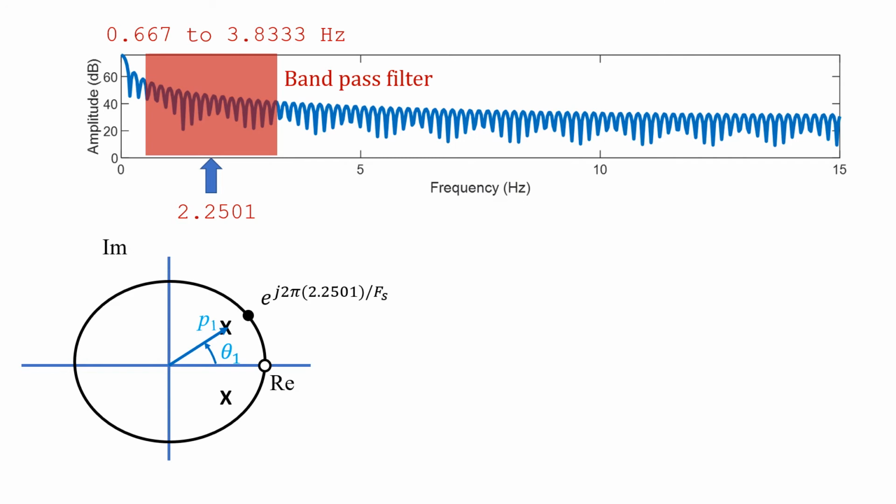If I want to improve my filter, I can add a 0 at that position, and what that 0 is going to do is take care of this strong peak here, the one at 0 frequency. So notice that that 0 will add this part here in my expression of H(z), and that r1 is the distance, once again, between that 0 and that black point in the unit circle at different frequencies.